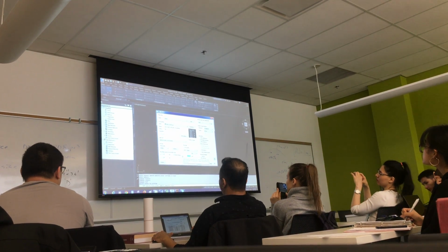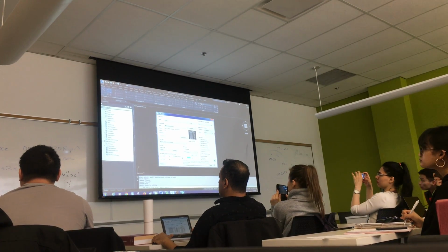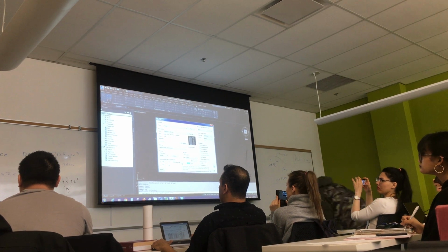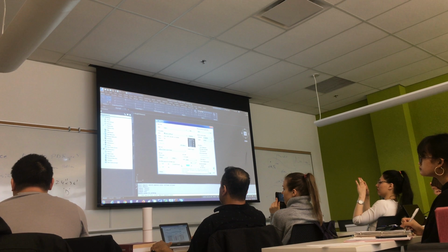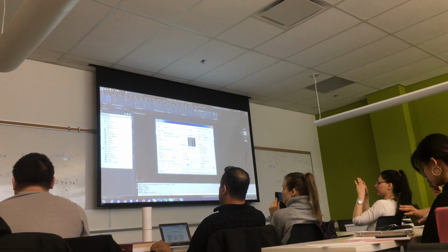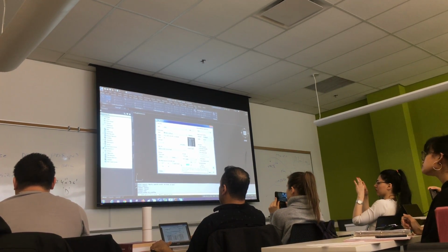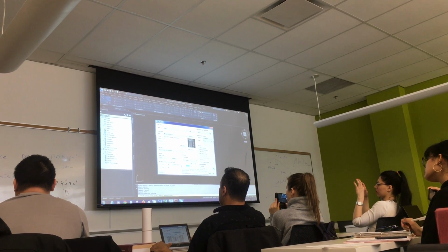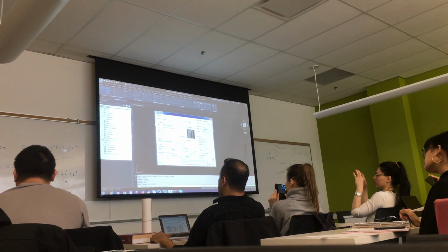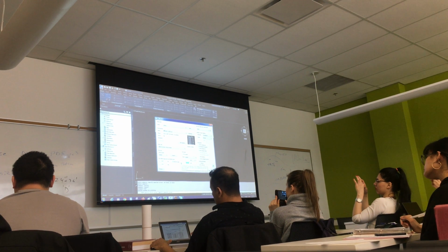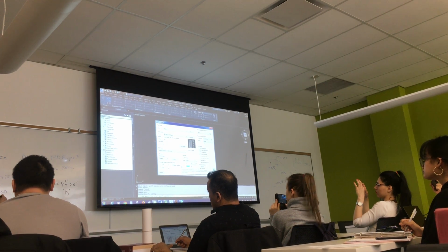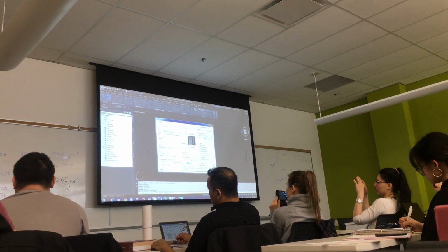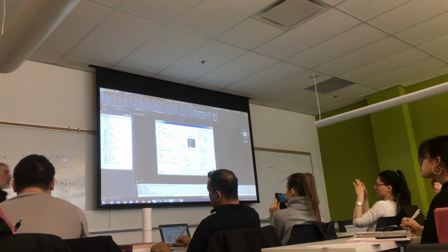Okay? The original software was designed for architects. They used to use millimeters instead of meters. So 1 to 1,000 is 1 to 1,000. We're doing meters, so we have to divide the scale. So if I want to draw on paper, 1 to 1,000, my plotting scale has to be 1 to 1, divided by 1,000. Okay? So if I want 1 to 100, divided by 1,000, it's 1 to 0.1. This is your plotting scale, so that you can get 1 to 100 on paper.